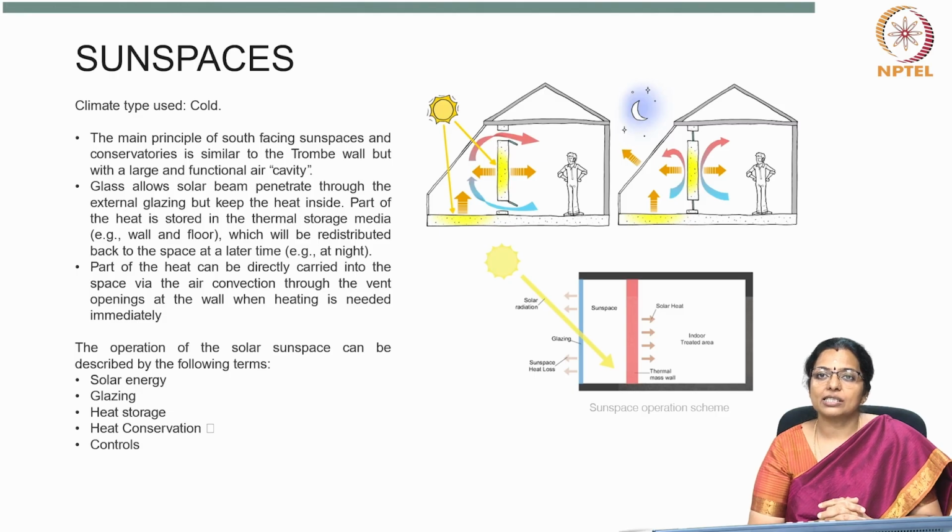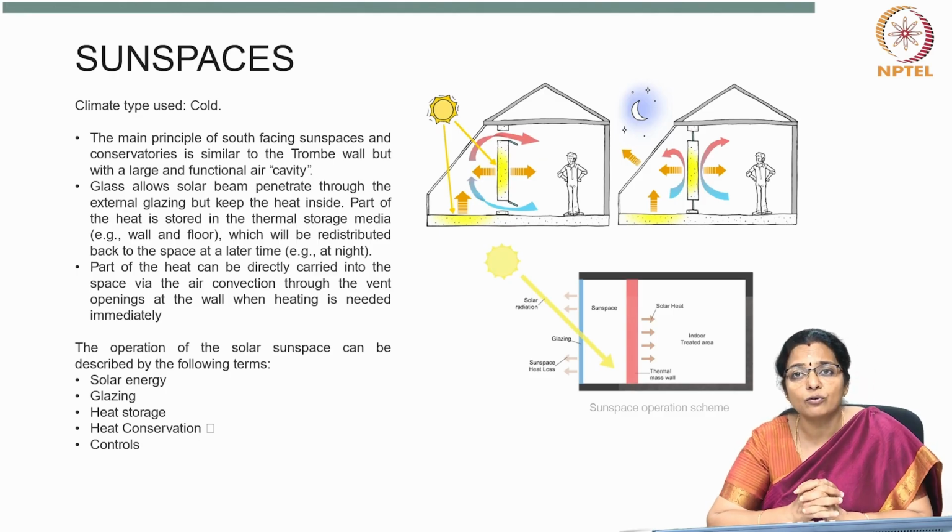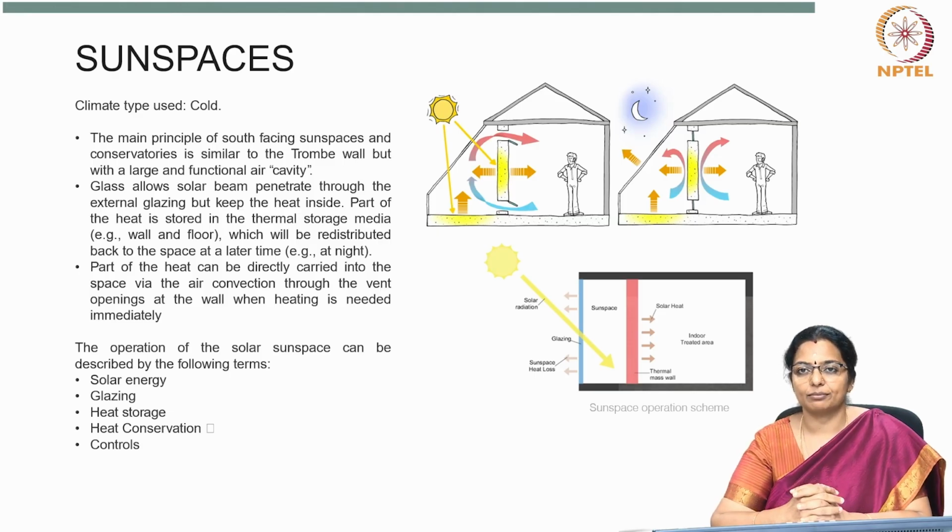Radiation heat losses, especially through the glazing, are a significant contributor to the general sun space heat losses. Then you have losses through glazing. The most common measure to increase heat flow resistance through the glazing is the use of double glazing that are separated by a thin layer of air. The air layer functions as insulation.